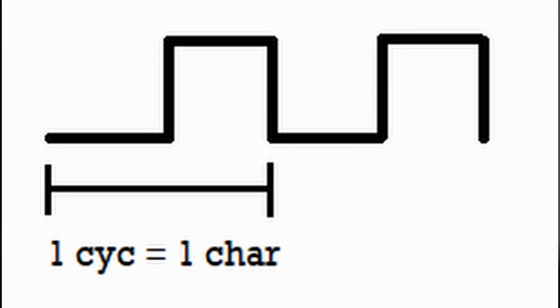So yeah, it's displaying half character glitches all the way across the screen. And basically what we think is that the CRTC tries to change things on a half character basis. The clock is set to a frequency which does a full cycle every character, but of course it's changing from high to low and then back to high again every half character.